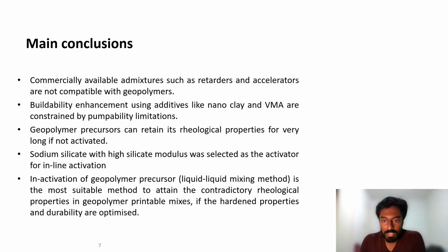The liquid-liquid inline activation method is currently the best method because we have pumps to pump both the liquid ingredients at a precise dosage. Dry-liquid could be better, but we don't have a pump to do it. But when you have two liquids, the total water content of the mix increases significantly, which can be detrimental to compressive strength and durability. But we can always change the geopolymer mix design because it is highly customizable and get the hardened properties and durability required.